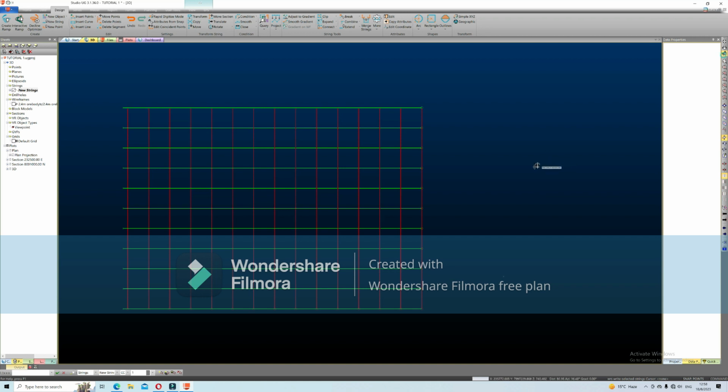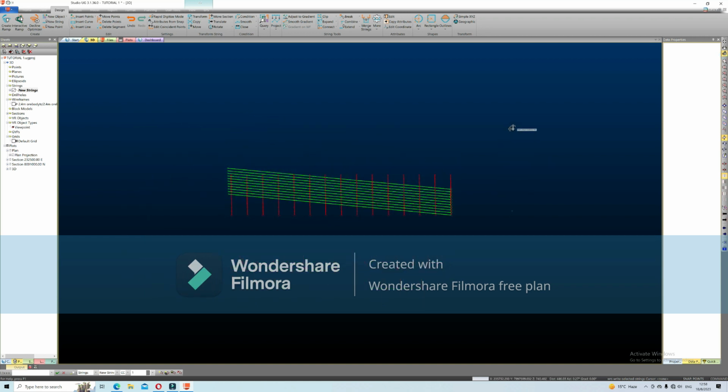So if you try and rotate this, you're going to see that some of the strings are already offset. You were designing this on plan, but some of these strings are already offset. So you need these strings to be aligned with the shape of the whole body. So first of all, we have to remove any duplicate files if there are duplicates on this design. Then the second thing that we're going to do, we're now going to project this string onto the whole body. Then from there, we now process our design, giving it the naming conventions, the design dimensions. Then we edit the dependencies.